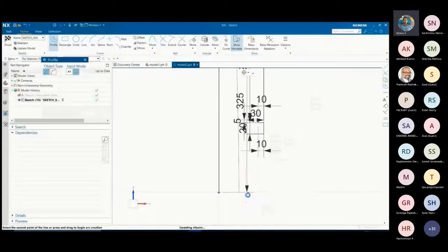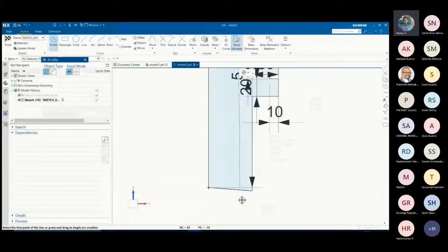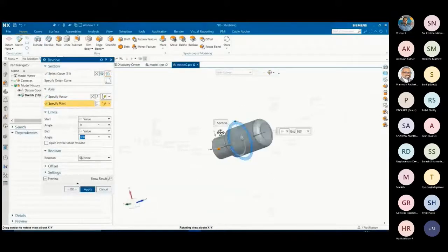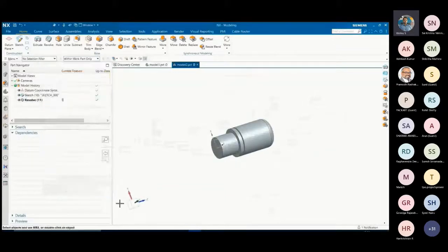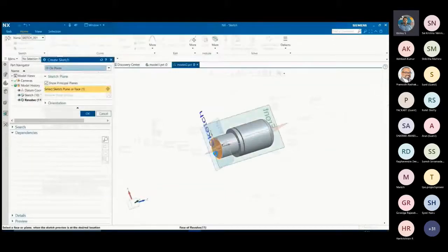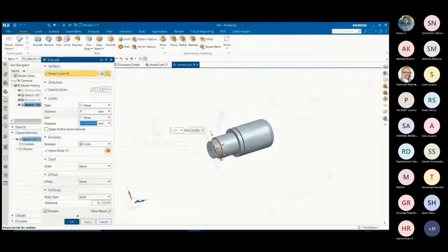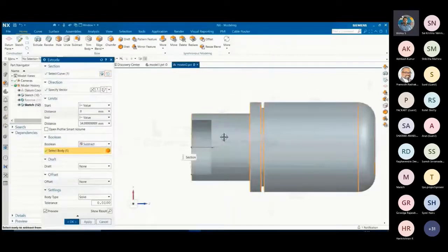Also, we get a collection of persistent and non-persistent geometric constraints that can be used while sketching. The commands in NX are always grouped pertaining to a specific workflow that imparts certain logic. So be it sketching or even in other applications. Even the Boolean operations are built into the extrude or revolve commands as well.